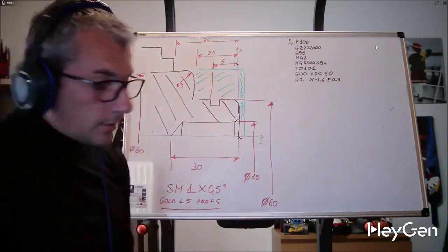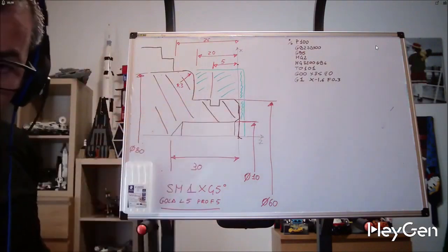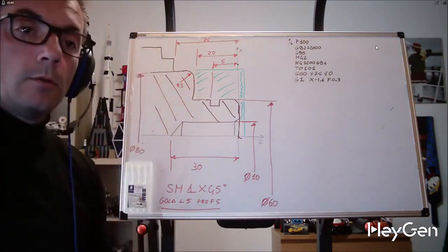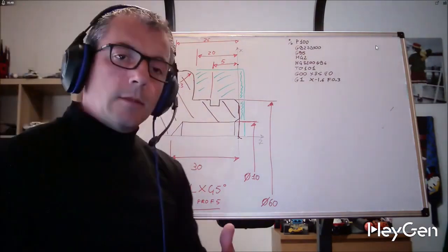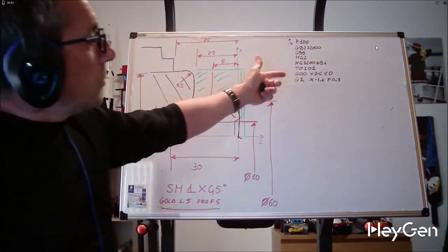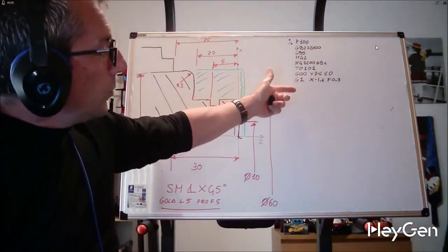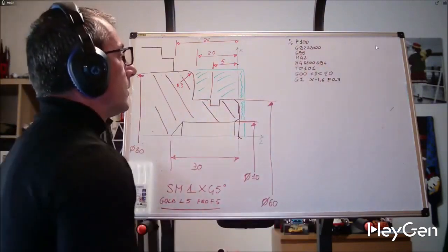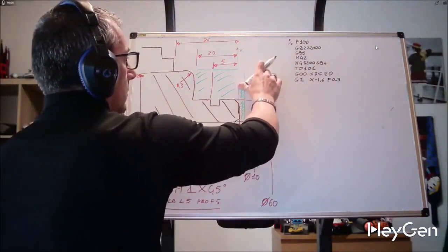In fact, I always recommend reaching X10 and slowing down a bit, because if we have the tool high or low, we could stress the tool tip. I provide you with this information, even though programming is more about tooling, but it's good to know. So normally I program G1 X10 F0.3, then to X minus 1.6 F0.1 to avoid stressing the tool tip too much. Well, I have already faced it, so we have already eliminated this part.